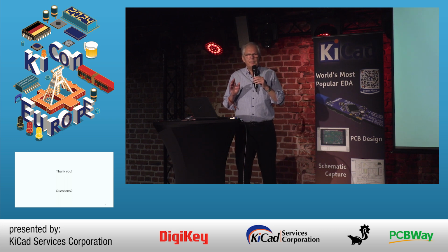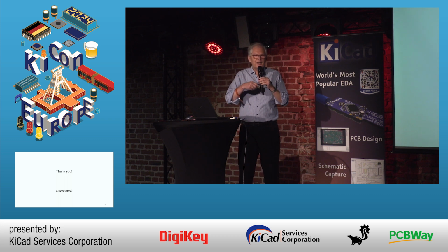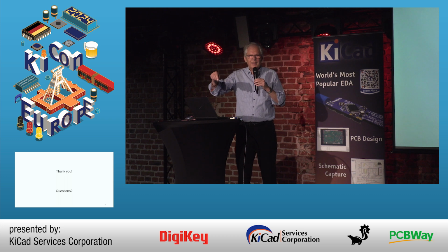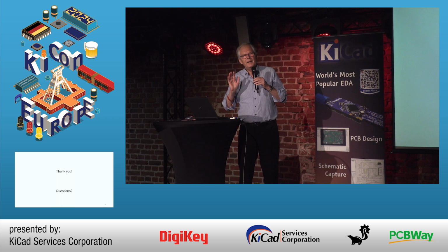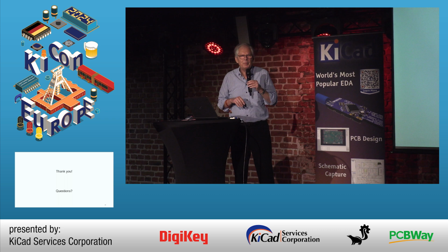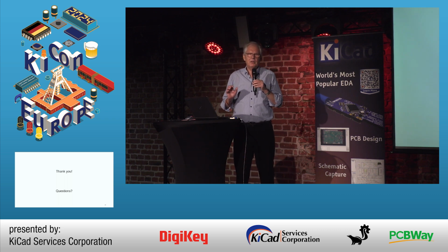If we talk about boards, I think the critical issue, and there is some work going on, but it's not yet finished, is extracting the parasitics. How much capacitance do you have? When you send a signal from the output port to some other device, what will happen? Will it be reflected? This modeling is tricky. Electromagnetic solvers are to be involved. There are some things going on, but this is not user ready right now. So I would say for the ngspice simulator itself, if you have the correct device models, no limit.